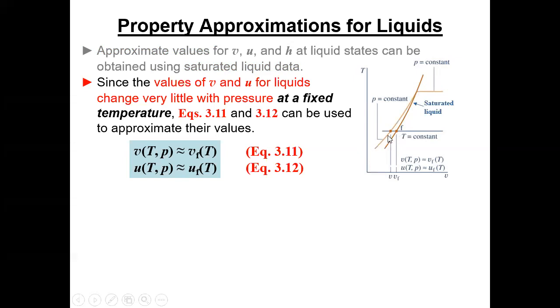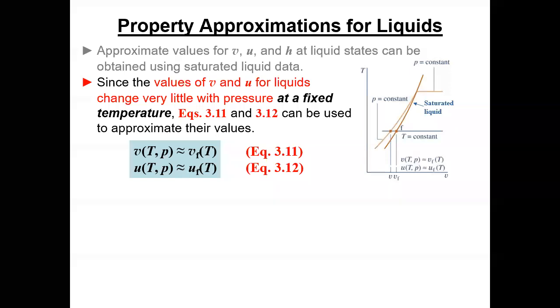So we're coming up and then we've got a line across here, which is a line of constant temperature, okay? So at this temperature level, if we're on that dot right there, that's the saturation condition. Okay? That's just saturated liquid water. And we can go to the tables, and if I could get to the tables, I would, but I can't, so I'm frustrated. But I'll get over it. And so whatever temperature this is, you can go to the saturation tables, and it'll tell you what pressure that is.